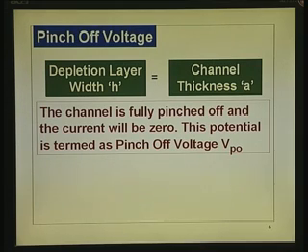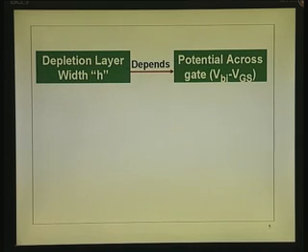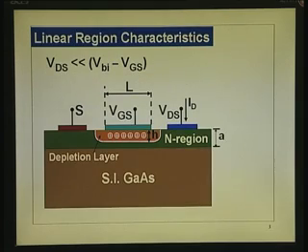Okay. I will just go back to this once to see the thing. You are finding out how much should be the potential drop across the junction, so that the depletion layer comes all the way up to this insulating layer. So, it is closing down entirely. There are no carriers present anywhere in that region. Between the source and drain, complete layer is depleted. So, what is the potential across that? Not the applied voltage. What is the potential across the depletion layer, so that the channel is completely depleted. That is what we call pinch off voltage.